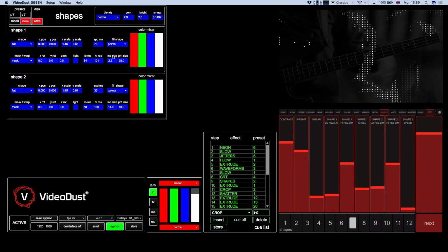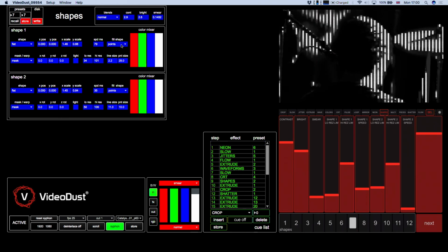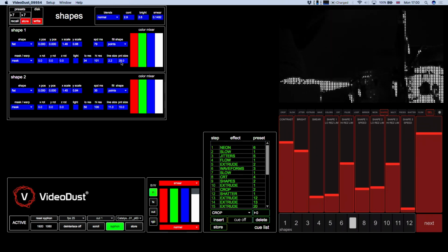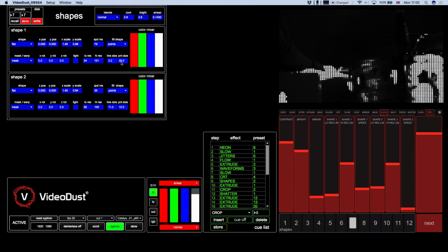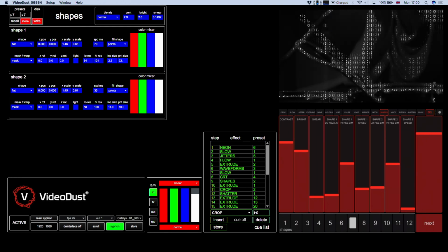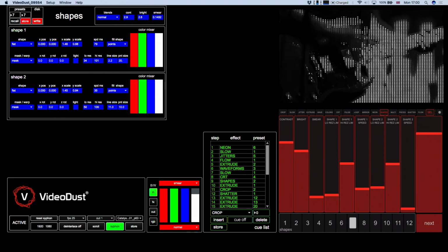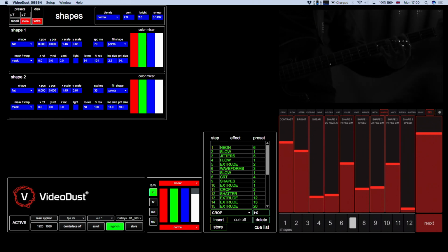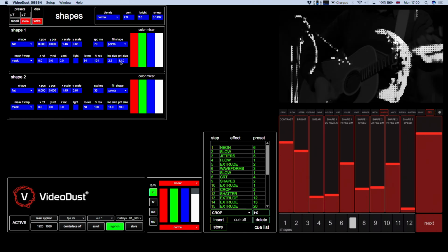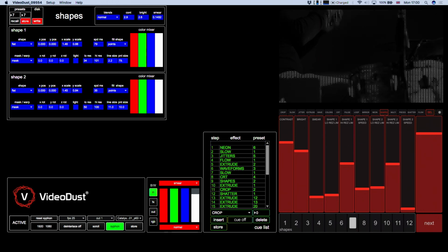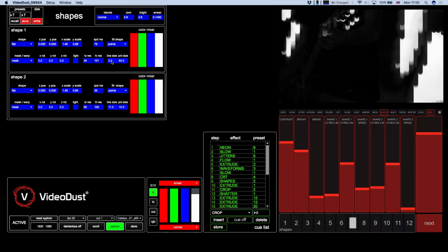And one thing to point out with the line size and point size, because we're using points in the fill shape, the point size defaults at 0 for the low. So when you set it to 28 here, that is the high range. So it always randomize from 0 to whatever this number is set to. So if I increase that quite high, say 80, it's stepping through at this speed from 0 to 80. And that goes for the line size as well.